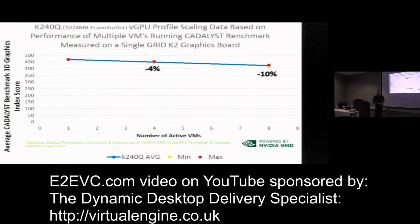So let's ask the question, what happens when we load multiple VMs on? We'll take the same card, the K2 card, set the 1 gigabyte frame buffer size, and stretch it out and see what that R720 does when you have 8 VMs running simultaneously. You get about 10% overhead running the AutoCAD Cadalyst benchmark. So this is an environment where the system is fully busy. You're continuously computing AutoCAD in all 8 VMs, and the overhead is about 10%. Which, again, I think is reasonable to get 8 VMs simultaneously on that server.